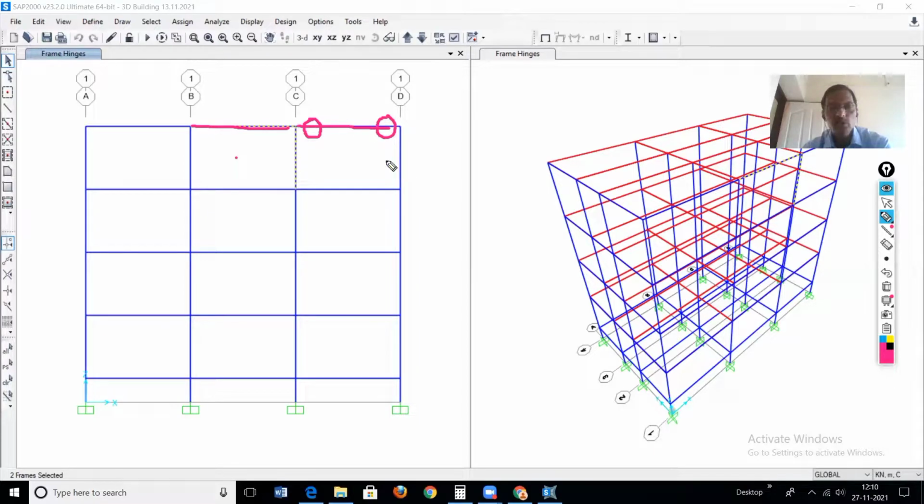If we do this option, that is, material nonlinearity defined at the ends, then this is called a lumped plasticity approach. Studies from various researchers say that whether you go for the lumped plasticity approach or the distributed plasticity approach, the results are very closely matching. The simple approach is the lumped plasticity approach. In this case, we'll choose this particular option, the lumped plasticity approach.